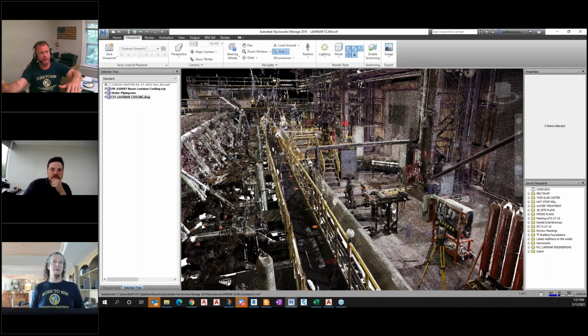We're going to scan the whole thing. We're going to prefabricate both the headers, both the 44-inch and the 28-inch header, still in the driveway outside. And we're going to take it out there and we're going to fit it up. We're going to make sure that piece fits. That's a job killer, to make 190 field welds in 20 days and try to get it fit up properly off of 2 headers. It's a big job.